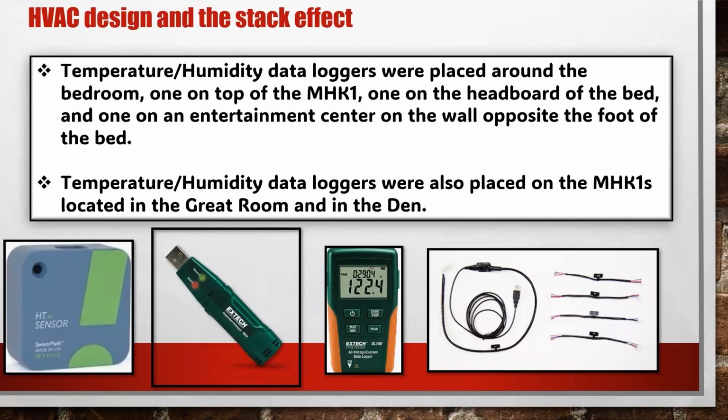Well, the DSB is great for a lot of things, but sometimes the numbers aren't correct. You really should go to the engineering manual that would show you the chart for the capacity output at different temperatures. I just had one last week where the numbers didn't even come close to what the engineering manual said. That's going to trump the DSB.